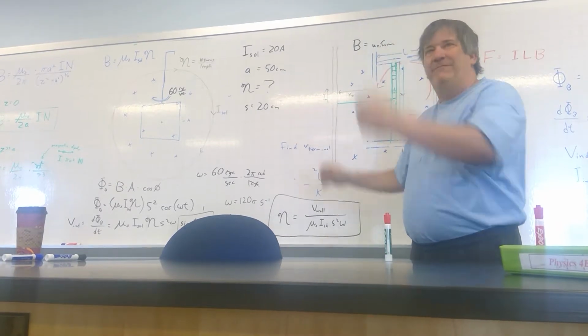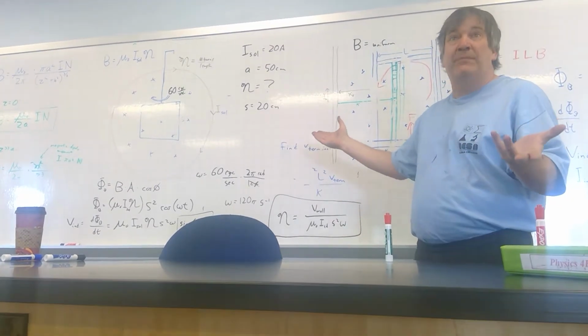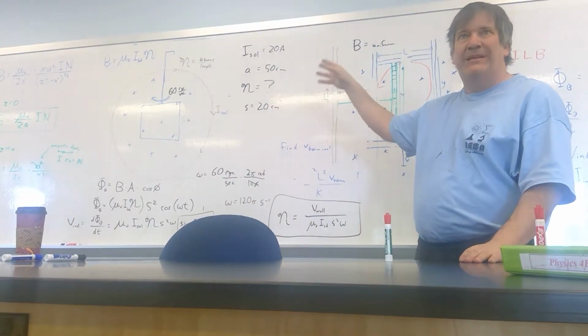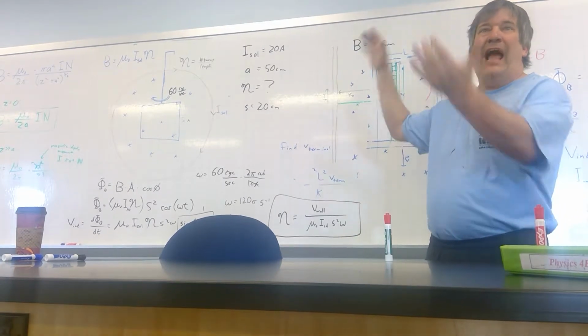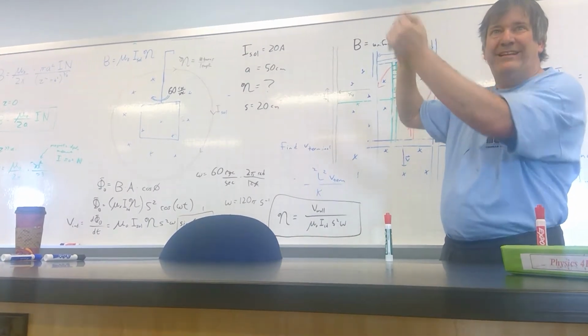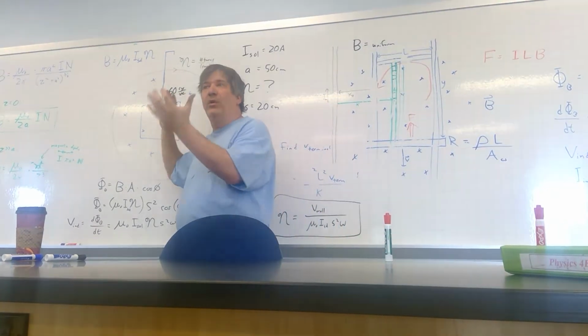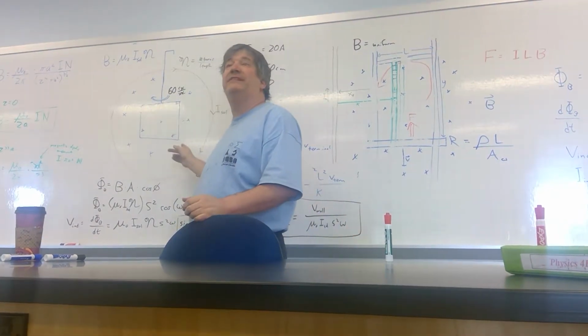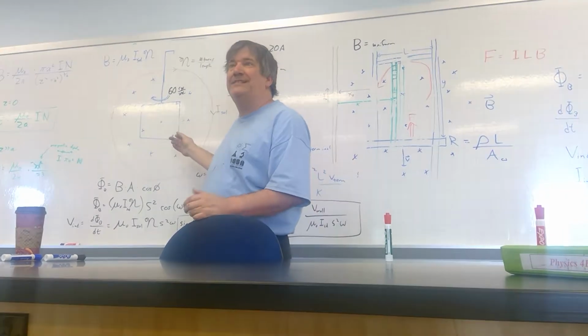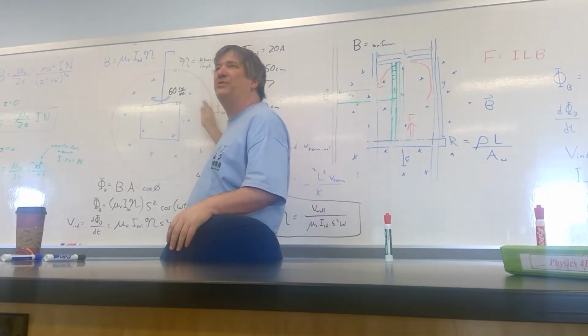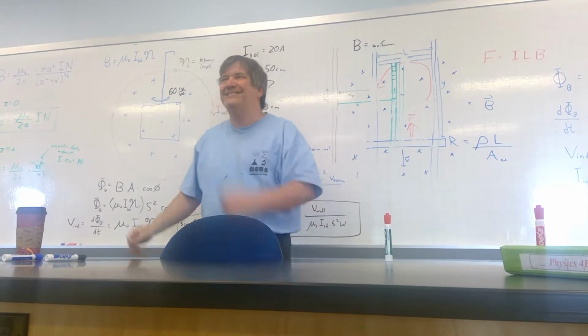But no, in practice, you're probably right. I probably wouldn't use a solenoid because that's a powered device in itself. I would probably use a powerful permanent magnet and be spinning this thing next to the pole of that permanent magnet. The disadvantage of that for an exam problem is that permanent magnet might not have that wonderful uniform B field that a solenoid has.